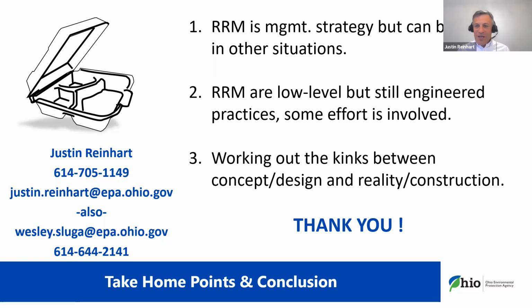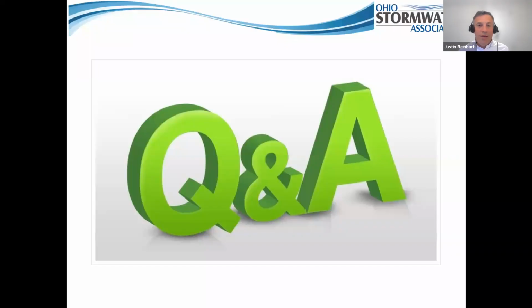Does the type of vegetation cover, cut grass, or prairie modify the credits shown? Well, that is a distinguishing factor. If it's cut grass or maintained lawn, that should be a filter strip. Prairie grasses that are not maintained, not mowed, outside of maybe occasional maintenance, upkeep, invasive species, something like that, those could be conservation areas. Much deeper root structure occurring, much more interception, higher quality of vegetation, you might say.